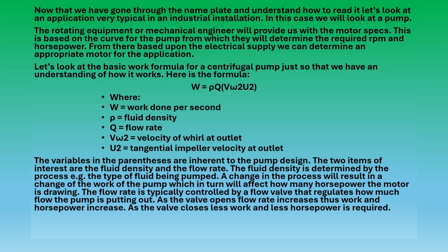If so, that can increase the workload. The other thing is, have they increased the flow rate? Either of those two will increase the horsepower required, which will cause a motor to draw more current, and well, it can cause a motor overload to trip.